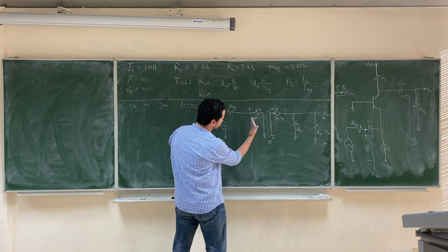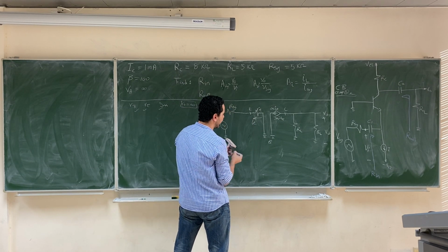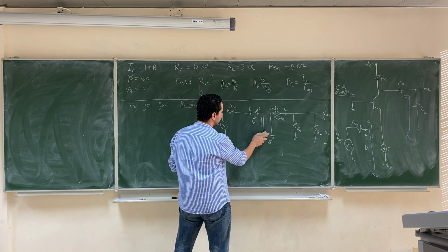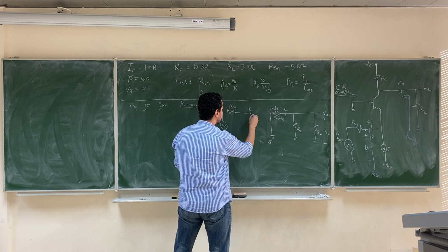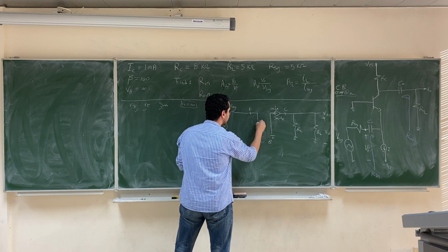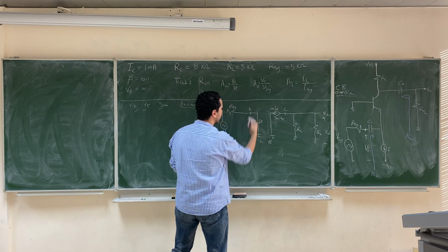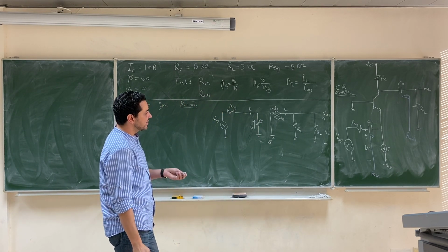But remember, if you get this resistance vertical, i.e., IE is going from the ground, which is from the base up, right? So you can plot this like this. You can put a resistance RE here, and IE is the current going from the ground up. Now the circuit is kind of familiar, easy to analyze.